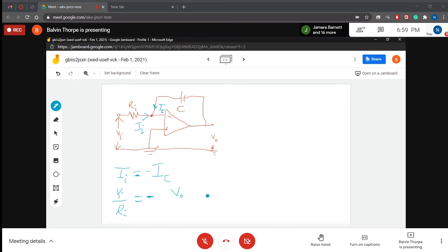The capacitor will block only if it's DC. But our VI is AC, because the DC was already used, assumingly, to bias the transistor. So now we're applying a real signal for amplification purposes, right?